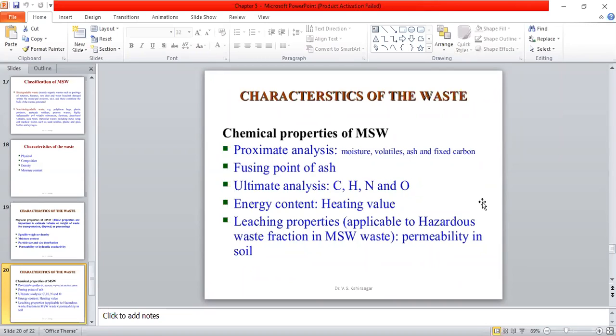Means, in simple language, I would like to tell you, biogas is a composition of methane, carbon dioxide, H2S, and some quantity of water vapors. So water vapors are not going to be burned. H2S is not getting burned. Then carbon dioxide is also not getting burned. Rather, the carbon dioxide will hinder the burning or control the burning. Is it? And then the next one that remains is CH4, which is the only burning gas.